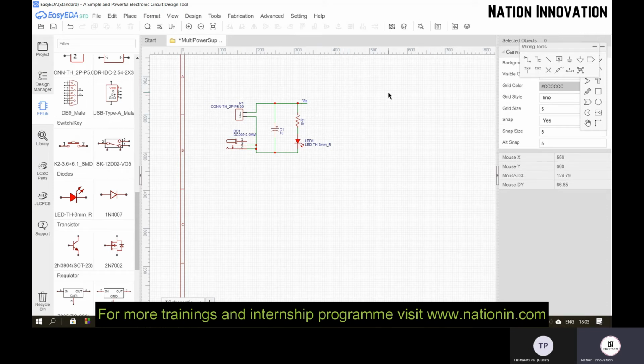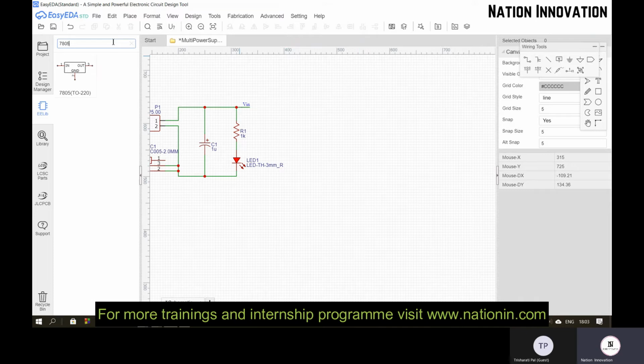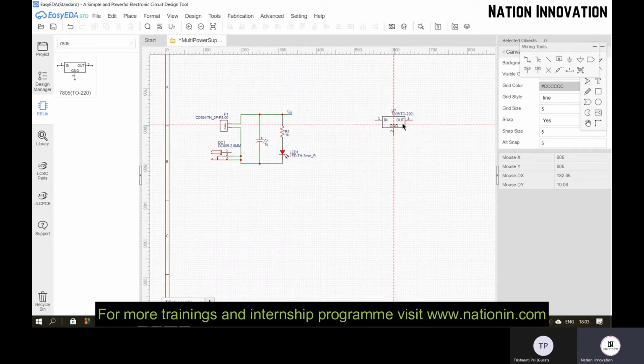So in next we will be designing a 5-volt voltage regulator which provides a 5-volt output by getting an input from this DC power supply. So for that we need a 7805 IC which gives a 5-volt of output. For that, let me type 7805 here. This is our 7805 TO220 pack. So you need to select that 220 pack. There are many packs. We need a 220 pack. So select that and place it somewhere here.